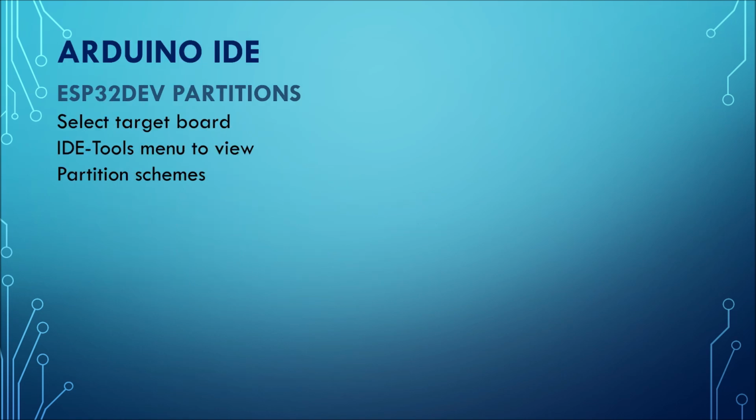So with ESP32 partitions, it's quite easy. You select the target module such as the ESP32, you then go into the IDE tools menu and you see a whole lot of partition schemes that are available.